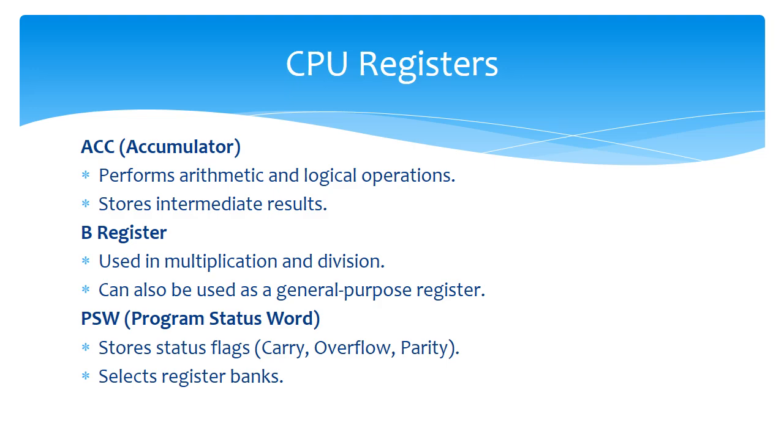And this program status word also has some bank bits that are called RS0 and RS1, the register select bits, which are used to select the register banks.